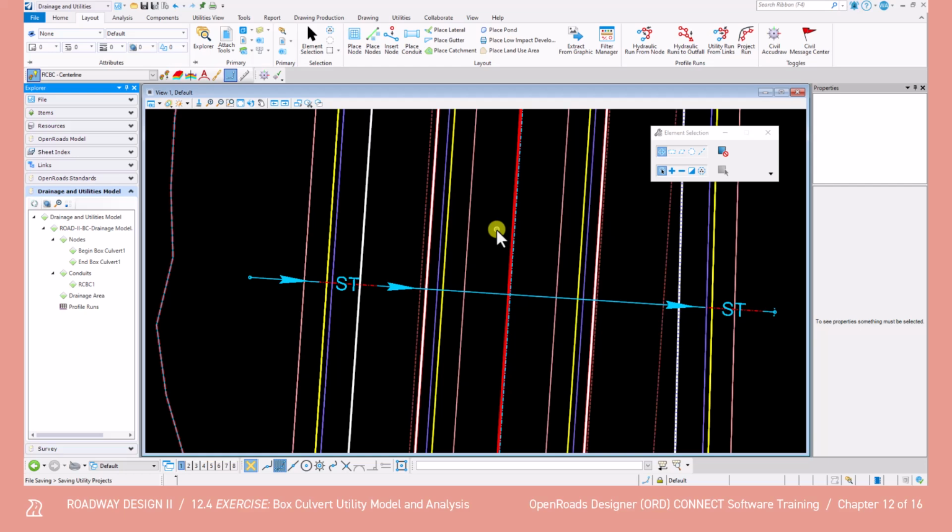The following steps discuss how to input flows for this culvert. For the hydraulic analysis, this exercise obtains the design flows from the USGS StreamStats. As an alternative, you can calculate the runoff draining to this culvert using the regression equations mentioned in the TDOT hydraulics manual. A TDOT survey file would also provide the drainage area for the culvert.